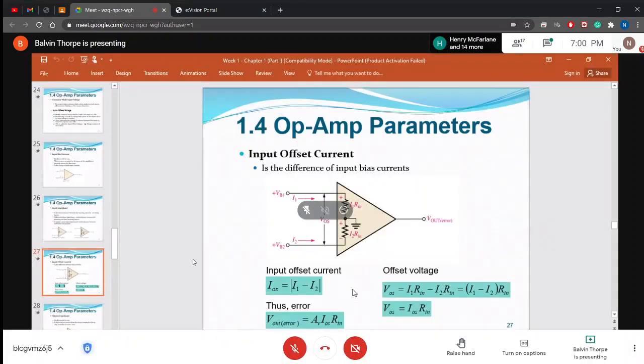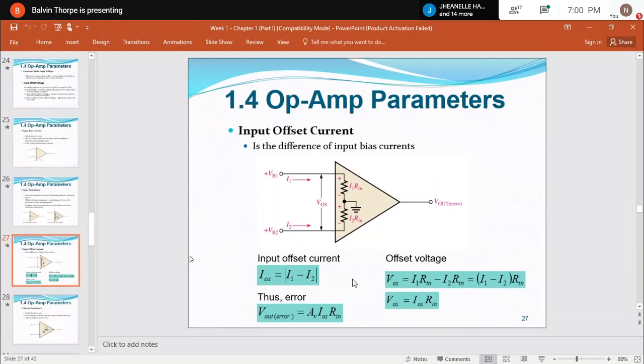So you say that it's been driven to saturation. Well, what we're saying here is that an operational amplifier, in this case, is operating in what is called an open loop configuration. In the open loop configuration, because the gain of the amplifier is so high, the output voltage is driven to saturation. We're looking at open loop right now on screen.